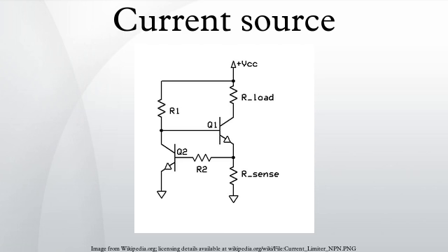If the input voltage varies, this arrangement will act as a voltage-to-current converter. It can be thought of as a reversed current-to-voltage converter. The resistance determines the transfer ratio. Current sources implemented as circuits with series negative feedback have the disadvantage that the voltage drop across the current-sensing resistor decreases the maximal voltage across the load.